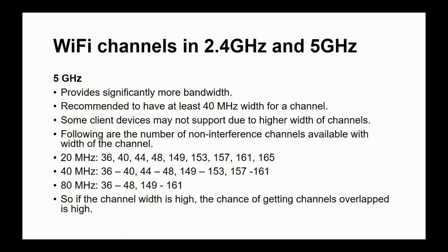As the 2.4 GHz band becomes more crowded, many users are opting to use the 5 GHz ISM band. This not only provides more spectrum, but it is not as widely used by Wi-Fi, as well as many other applications using items such as microwave ovens, etc.